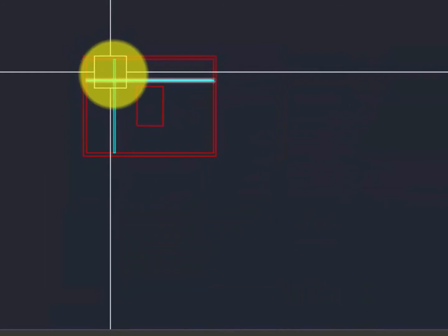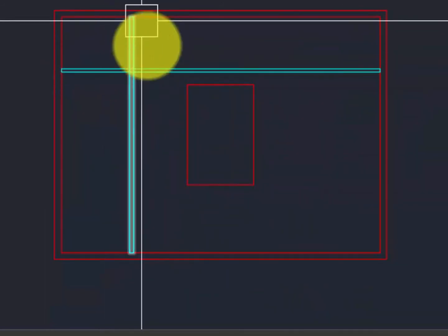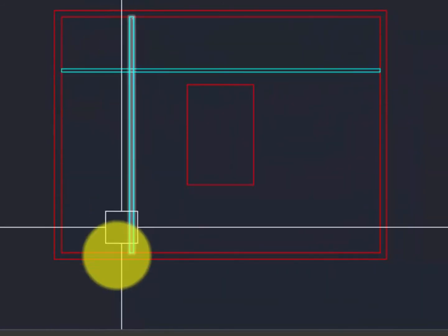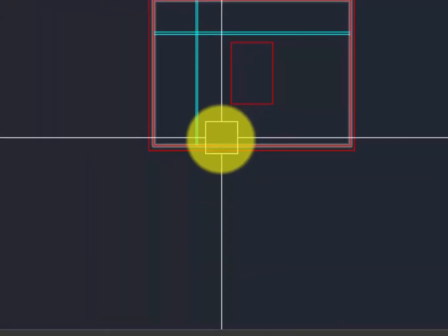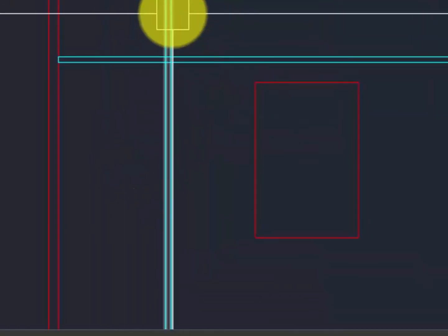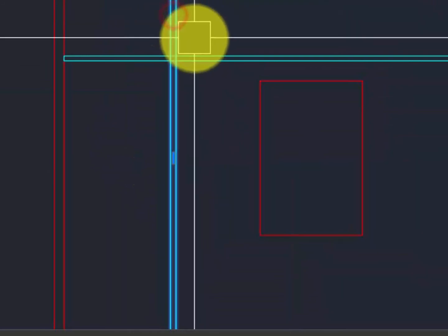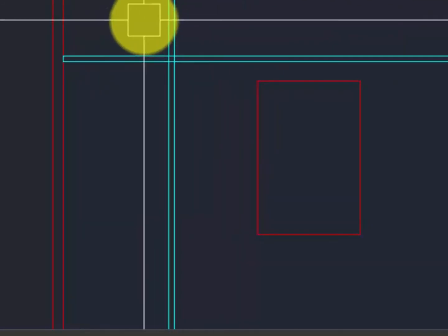Okay, so these are the two basically steel bars we are going to use. We don't need to draw all the steel bars over here from this line to this line or from this line to this line. Okay, so what we have done is that this steel bar has been placed at equal distance center to center in both longer span and shorter span.